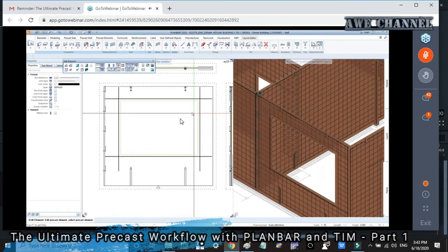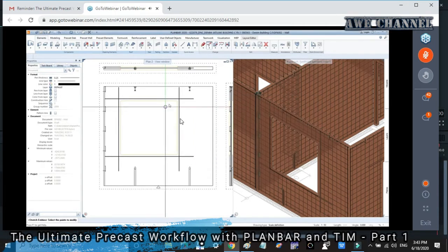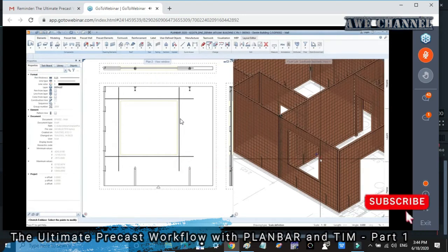And in case you have to resize openings, you can see what happened after this. The system will regenerate the position of the lifting bolt according to your CG. Even the extra reinforcement already moved. The position of the connector already moved because of your condition. So for the precast wall, we have a more automatic system to help you increase your productivity. Let's say, for example, if you want to build up the 3D modeling, we have a better tool for you to use.